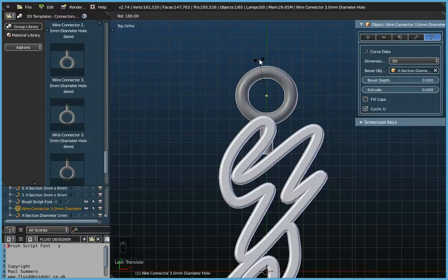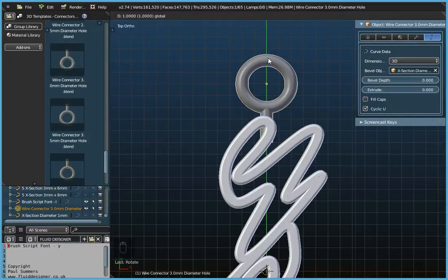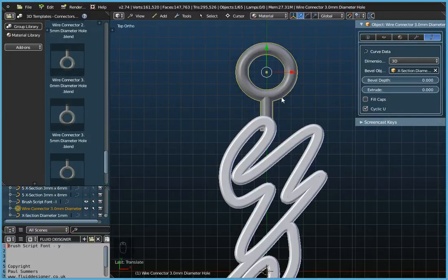and then I could click with the mouse, and up in the top of the window there, you'll see what the rotation is, and I do actually want a rotation of 180 degrees to get it absolutely right. So let me just position it so it says rotation 180 now, and I click the left mouse button. So that's one way of rotating it. Now I do need to position it more accurately, so I'm going to position it like that.